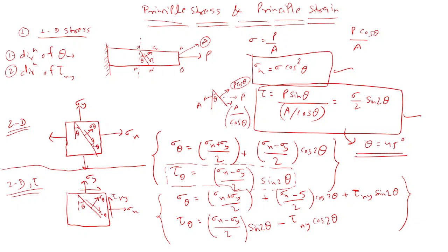Then from that direction, 45 degrees would be the maximum shear stress plane. That would also be asked to you in the question. General loading would be given, and it would be asked to find the normal stress at the maximum shear stress plane. Those types of questions we'll see later.